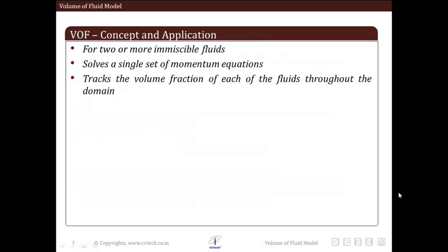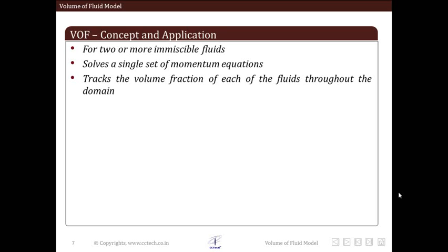Let us first understand the concept behind VOF. When you are using VOF, it is used for two or more immiscible fluids. It solves a single set of momentum equation for the mixture phase. Single momentum equation is solved. It does not solve different momentum equation for different phases. It tracks the volume fraction of each of the fluid throughout the domain. These are the three basic principles behind volume of fluid model.